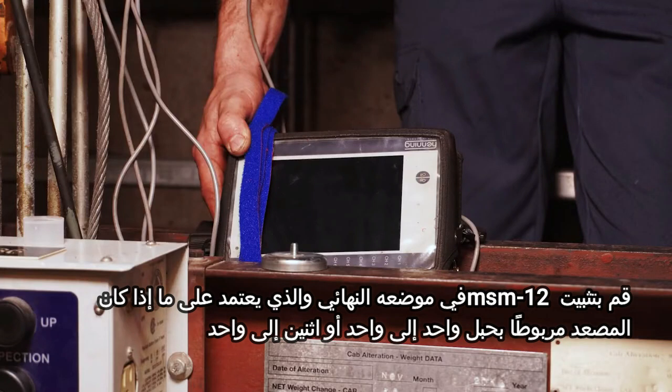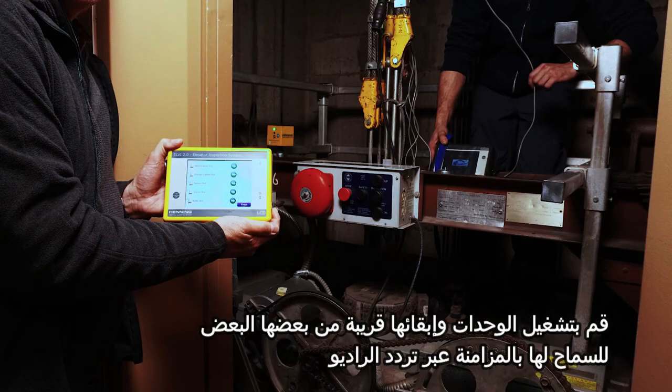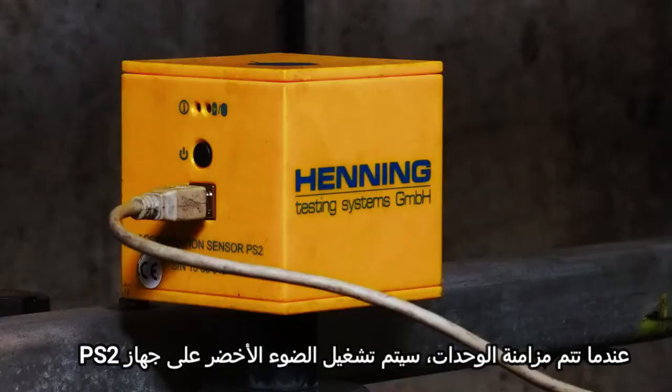Secure the MSM12 to its final position, which depends on whether the elevator is roped 1-to-1 or 2-to-1. Secure it with a strong strap and ensure it cannot fall or move around during testing. Switch the units on. Keep them close to each other to allow them to synchronize via radio frequency. When the units are synced, the green light on the PS2 will turn on.